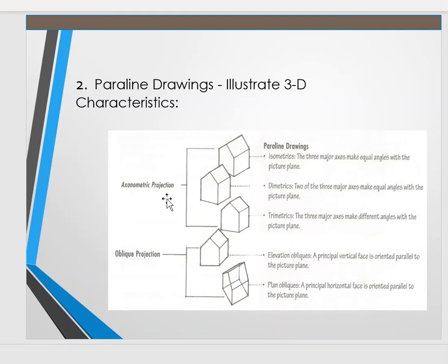But in an axonometric projection, you are taking an object, you're putting it at a slight angle or different angles and projecting lines that are vertical, connecting the dots and creating a three-dimensional item. The axonometric projections are based on three different types of angles, but the number one most common is isometric. That's just the perfect, they're both equal. The di meaning two, diametric is two angles that are the same and one that's different. And then the trimetric is three angles that are different.